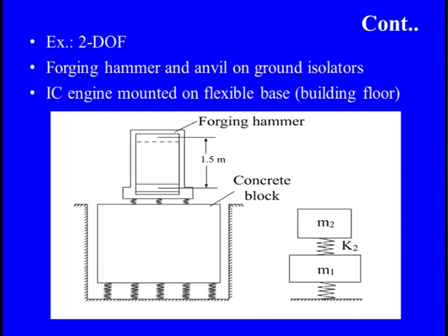The springs are there. We can say right now the spring stiffness is K1. The concrete block is on a certain surface, and it has some deforming features that can also be represented by springs. So right from the base we have the first spring of stiffness K1, then mass M1, then the K2 spring, and then mass M2. Here we have two independent displacements, x1 related to M1 and x2 related to M2. We can say this system falls into 2 degrees of freedom.